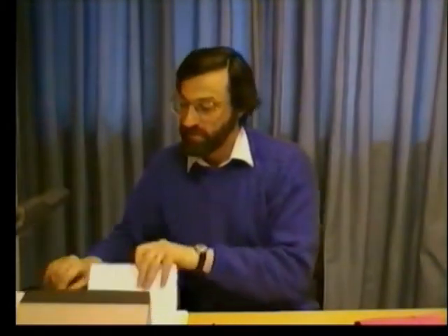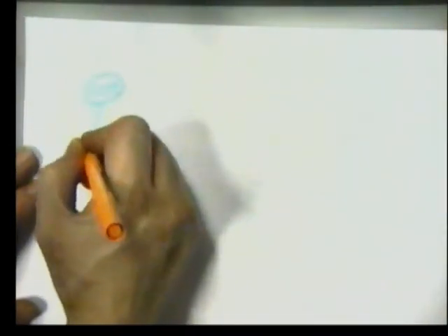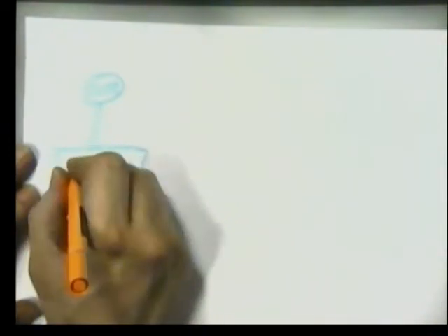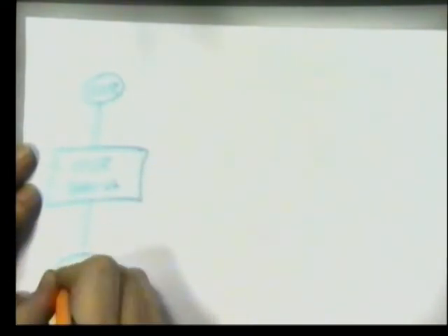So parallel processes have to have structures that allow data to pass between them, and we do that using a post box and a semaphore. So let's draw our processes again. Here we have our interrupt service routine. And here we have our interrupt service routine data. That is the basic concept of an interrupt service routine. And then parallel to that, we will have our background process.